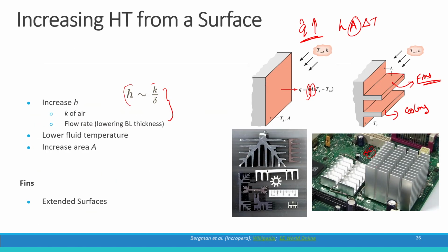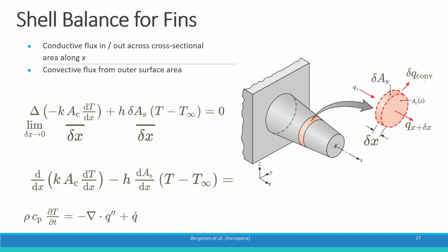So in order to derive the necessary equations that will help us to find the temperature at any given length of the fins or the heat transfer through the fins, we consider a heat balance across this elemental section. If I am considering this section, this is the direction x, so I can write it as qx, and if the thickness of this small section is dx, it will become q(x+dx).